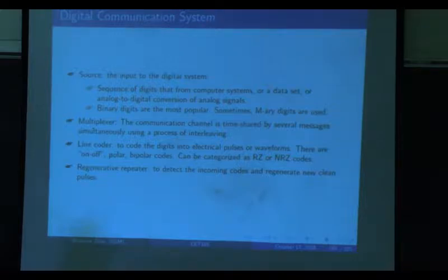For example, if you want to transmit 1101, how are you going to transmit that? One option we know from before is to use 5 volts to represent 1, so 1, 1, 0, 1 becomes 5, 5, 0, 5. That is only one of the options. The other option is, for example, ASK. 1 means we have a sinusoid function, 0 means we have nothing. We already know this from the labs. So that is also an option.